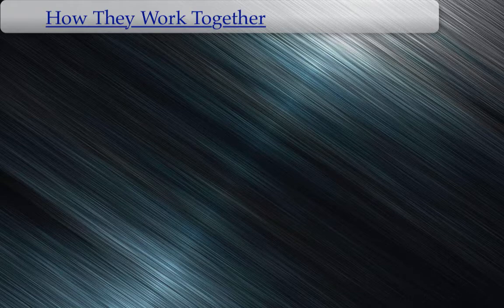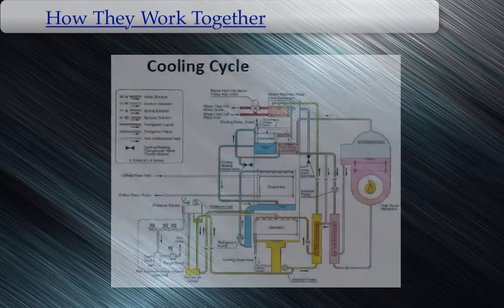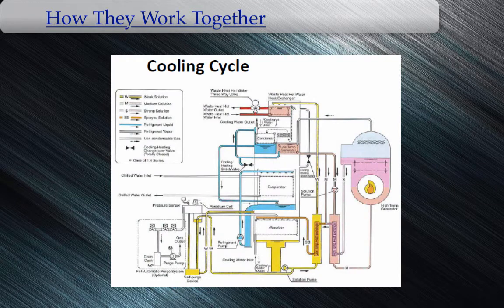How they work together. Several energy-saving methods have been incorporated with the absorption chiller. This hybrid system can run on either hot water at 196 degrees Fahrenheit provided to the low temperature generator, or clean natural gas supplied to the high temperature generator, or both of them together. The hot water loop can achieve a temperature of 196 degrees Fahrenheit from two different methods: exhaust gases from the high temperature generator, or solar thermal energy.